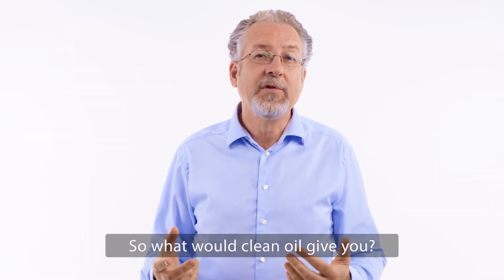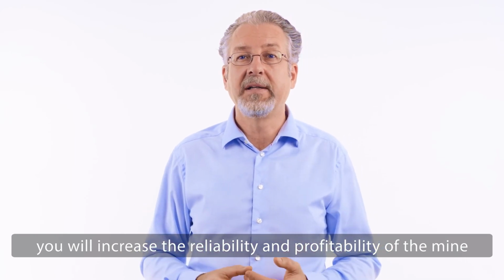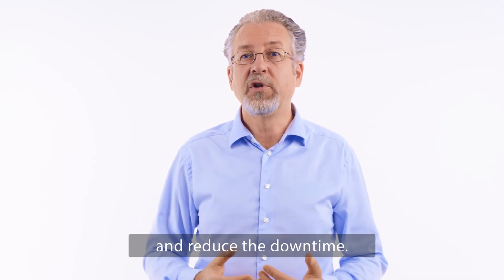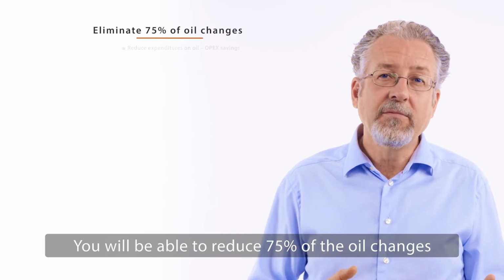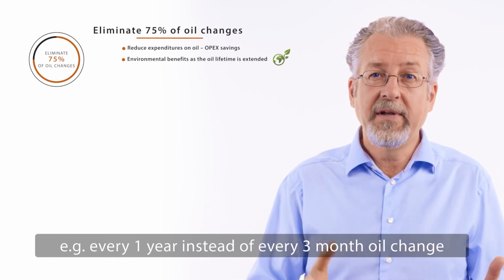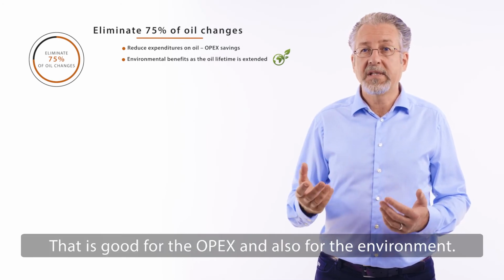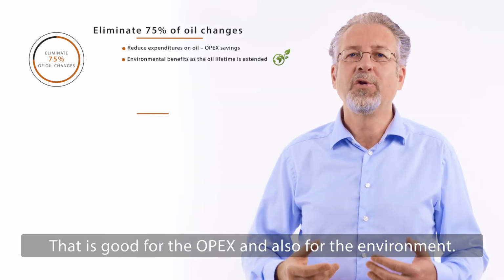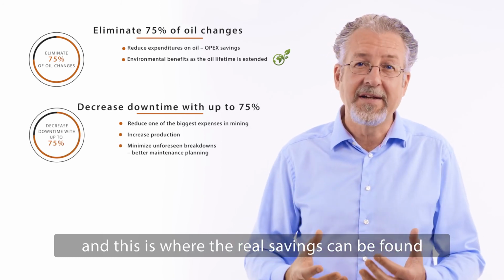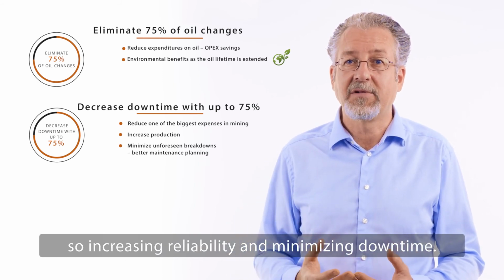So what will clean oil give you? You'll increase the reliability and profitability of the mine by having longer life on the oil and the wear parts and reduce the downtime. You will be able to reduce 75% of the oil changes. For example, every 1 year instead of every 3 months oil change on a crusher and mill. That is good for the OPEX and also for the environment. You'll be able to decrease downtime by 75%, and this is where the real savings can be found. So increasing reliability and minimizing downtime.